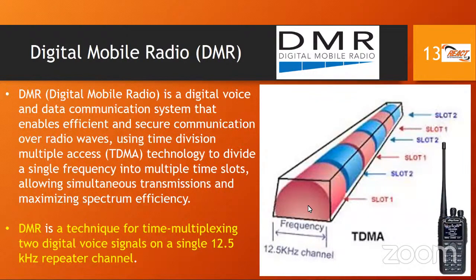That's pretty interesting. Normally you will have one signal on a frequency, but once you multiplex it, or use multiple access on the same frequency using time slots, you can have one voice going here and another voice followed by the same voice, and it's repeating. So it slices it up into time slots. And this is how it achieves multiple conversations at the same time.